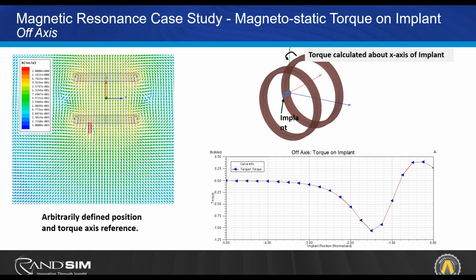And this is something now where we can bring in, let's say, some type of capacitors or other circuitry here that you would want to tune. So in this case with the MRI, we can use the 3D field solver for this level of simulation, then transition it into a circuit solve where you can now look at the impact of changing values in your different components.